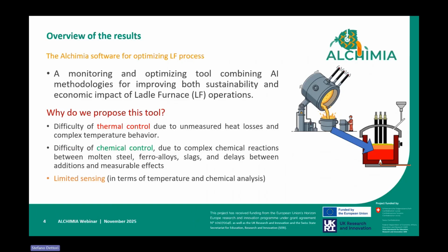In this process, operators add additional material to the molten steel, stir the molten steel through argon injection, and use electricity and a thermal system based on electricity to keep the temperature more or less constant to reach certain boundaries before the continuous casting. And we developed a tool for monitoring and also optimizing the ladle furnace operation, in order to improve both the sustainability and the economical impact of the ladle furnace operation.